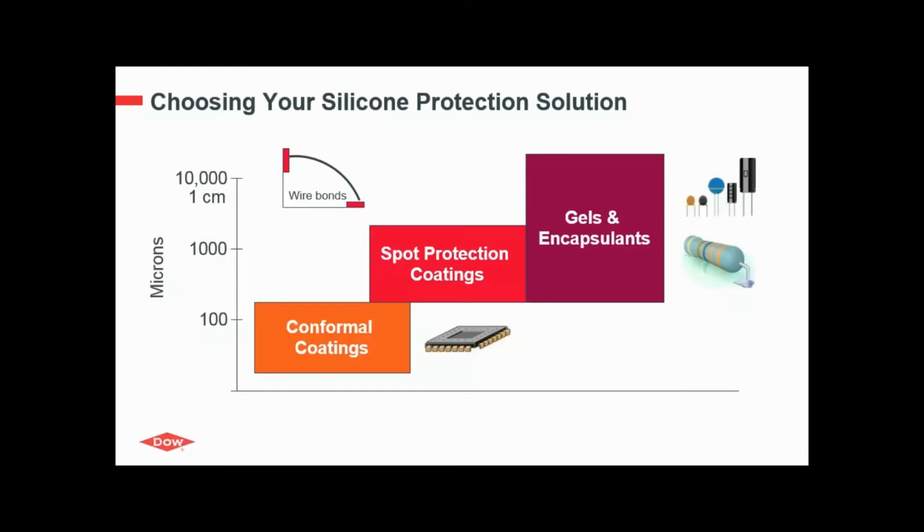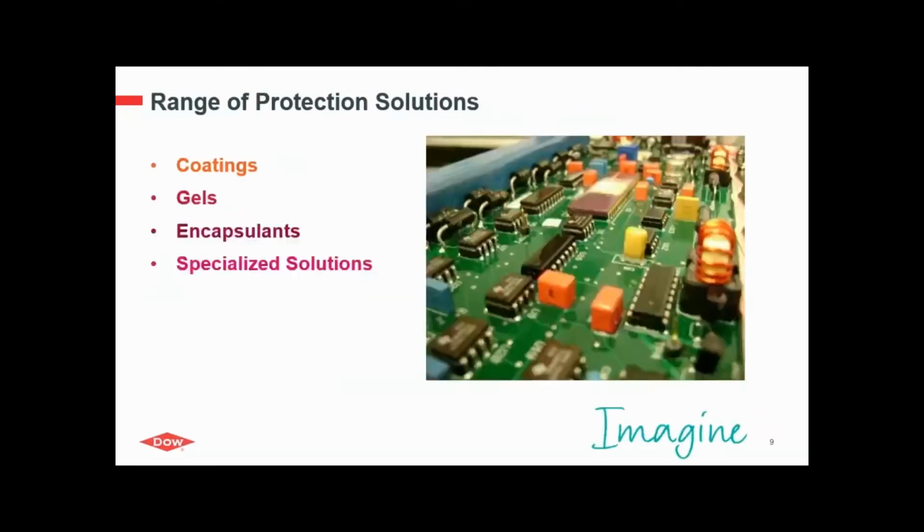And if you have a very complex landscape of components on your board with different sizes, you may want to choose a gel or an encapsulant in order to pot the whole module. So in the following slides, we would like to have a closer look into the range of DOWSIL protection solutions, starting with coatings, which will be presented by Thierry.